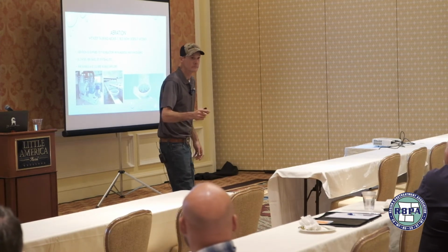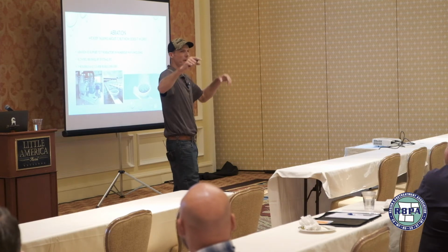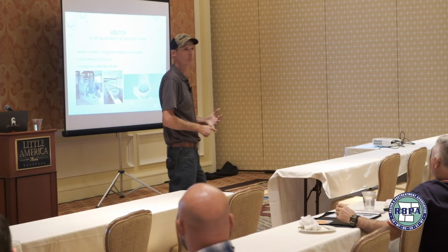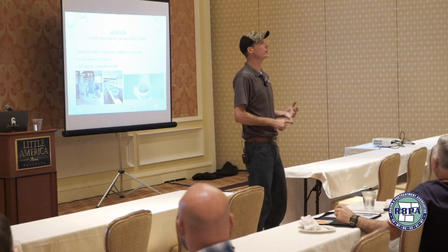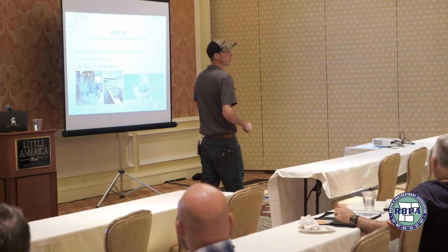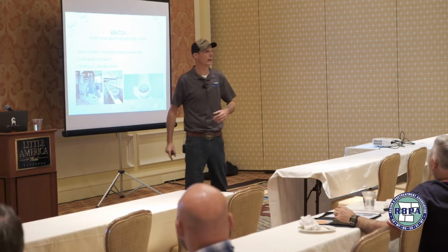Volatile solids reduction. That's what he said, for those of you that couldn't hear him. And what does the EPA say we have to have? How many percent volatile solids reduction in a digester before we can land apply the biosolids? I think it's 40%. 38, close. 38% volatile solids reduction in a digester before you can land apply it.